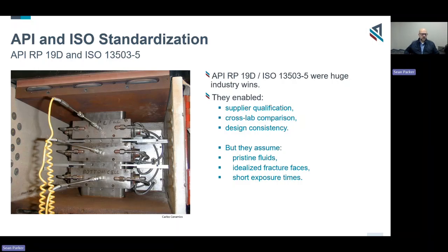Specifically, and from our testing standards, this is all relative to polyacrylamide-based friction reducers, but it can easily and readily translate into linear gels and cross-linked fluids as well. But those remain to be tested from our standpoint. But again, with these standardizations, there were big wins, because it then enabled people to qualify different proppants and fluid systems, and you had some mode of repeatability and design consistency.